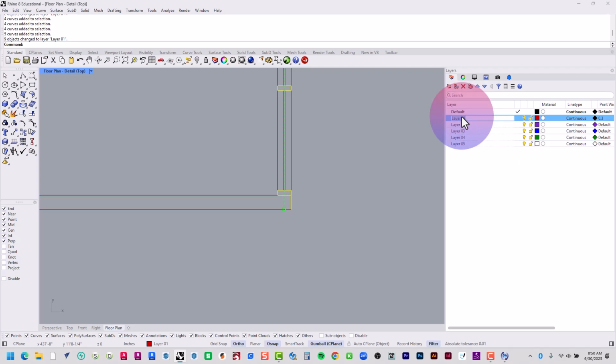And then let's do a layer for annotations. I'm going to move thin up a couple layers and medium up a couple layers. So now anything on this reddish layer is heavy. So when I do this and zoom in, you can see some difference in line weight. And now let's also put this one here on heavy. I'm going to change object layer.